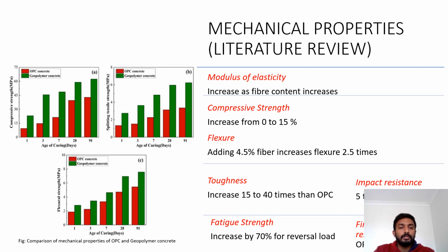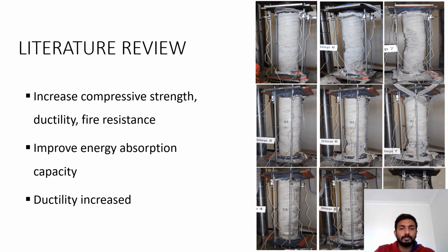As you see, the graph shows the OPC concrete and geopolymer concrete based on the property with the curing days that have been mentioned. The literature review that we studied shows the increase in compressive strength, ductility, fire resistance, and the improvement in energy absorption capacity. As you see in the figure is the loading that has been done on a geopolymer concrete column under various steps.